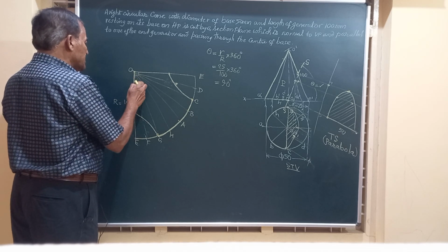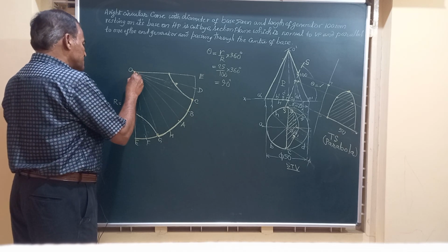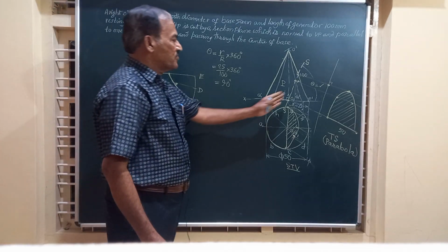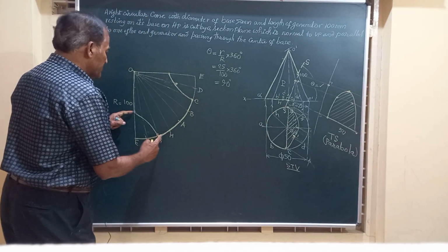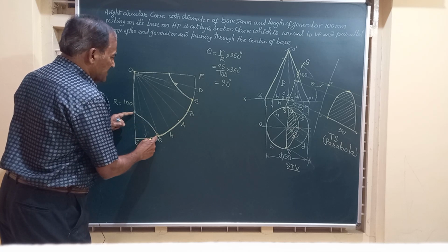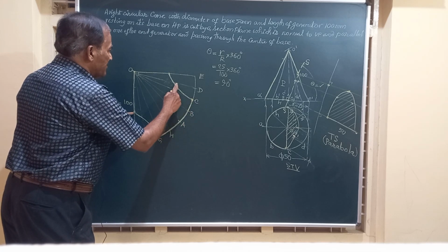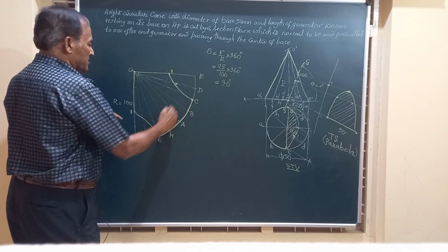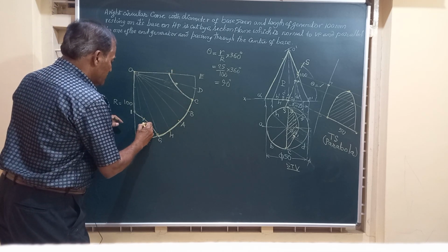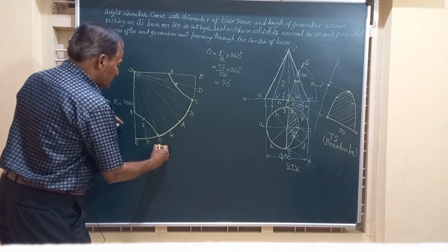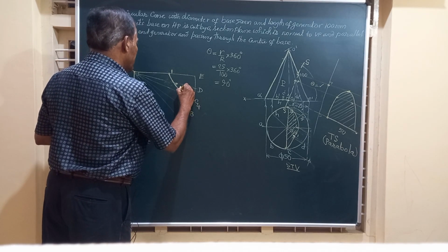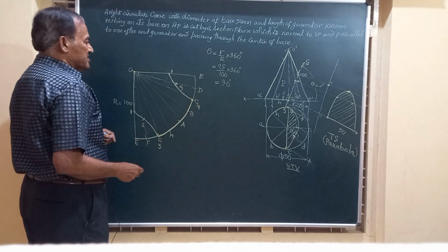Now after obtaining these points, this is how you obtain the development, friends. Since there is no place to mark, I will leave it. If you want, you can mark like this: 1, 2, 3, 4, 5, 1. So the first and last are going to be 1, 1. Then this is going to be 2, 3, 4, 5, because we got 5 points on this.